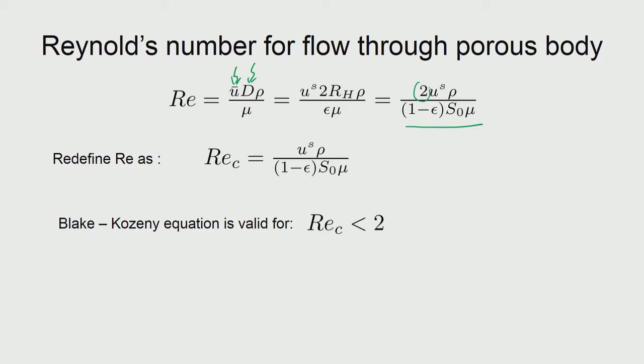Normally, when we have non-dimensional quantities, we do not want numerical things in there, because there is no point in that. We can look at the introduction of non-dimensional numbers as only a way to remove the dimensions, so numerical values need not come. So, we redefine the Reynolds number in this manner by knocking off the 2, and to remind us about the redefinition, we also pay attention to the subscript, which tells us that some redefinition has happened.